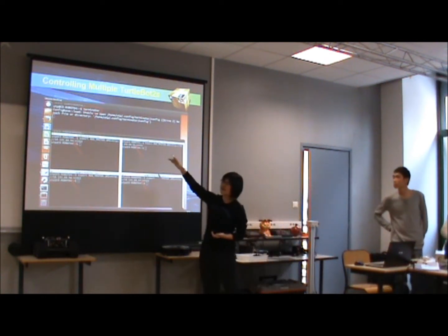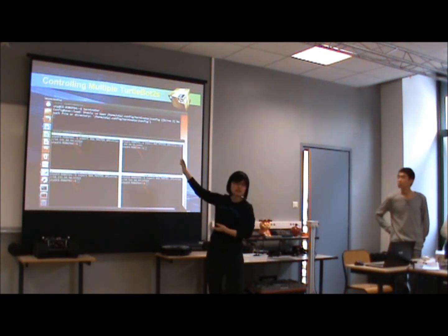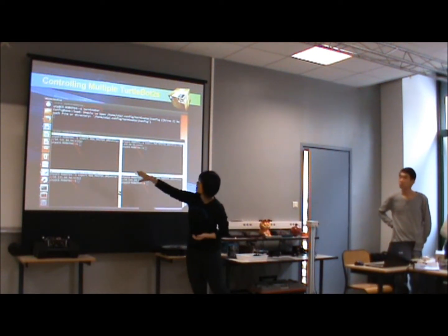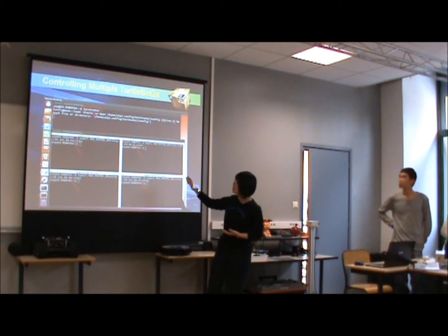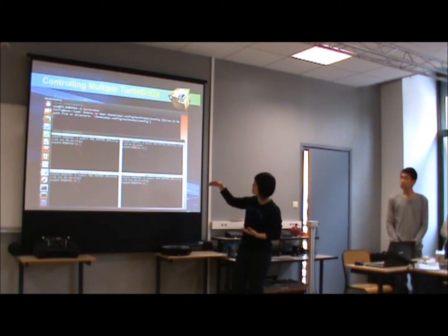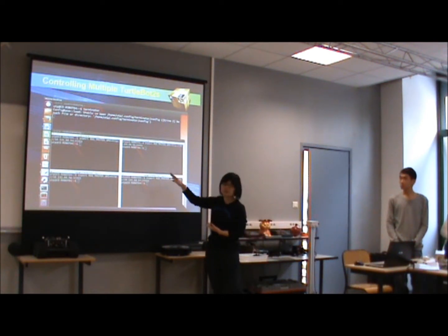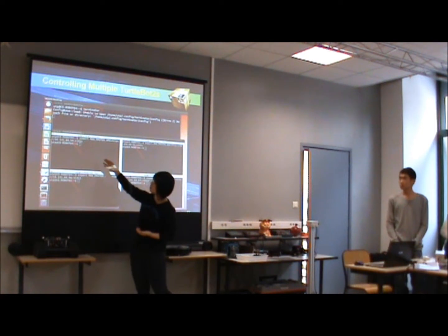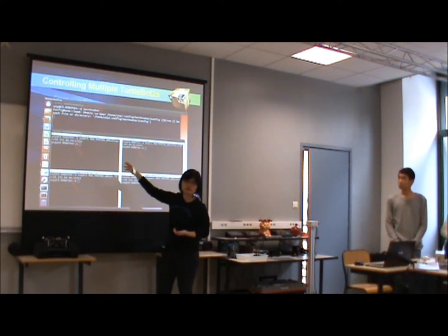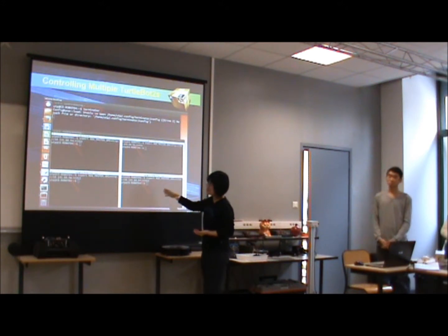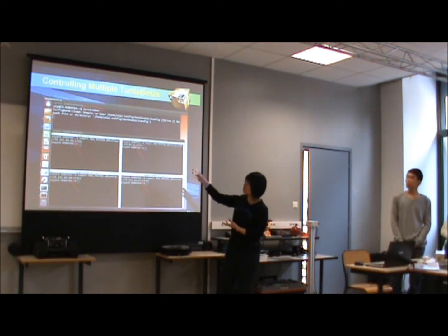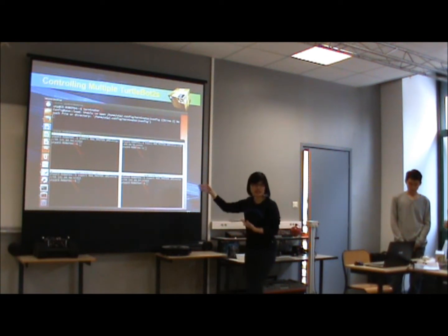This is the command that we can give in the normal terminal. When we just type terminator, a new terminal will come out, and in it we can split the terminals into as many as we want. In this case, I split it horizontally and also vertically, and I can put in the commands separately. As you can see here, I export the IP address to TurtleBot numbers 53, 55, 56, 57. So with this function of Terminator, I can address my commands to different TurtleBots, and I can have a look at the progress being made inside.